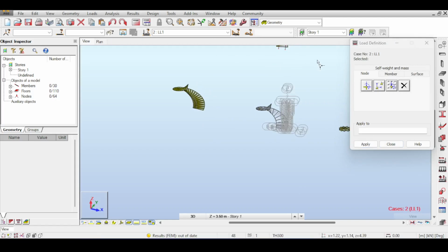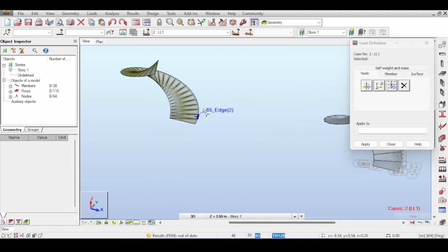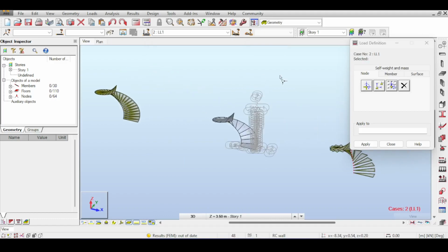Now, what is the live load on staircase? It is different than the live load on your story. Allow me to explain. So you see, when you design a structure, you usually select your live load based on code recommendations. For example, the ASCE has tables that talk about the live load for different structures.